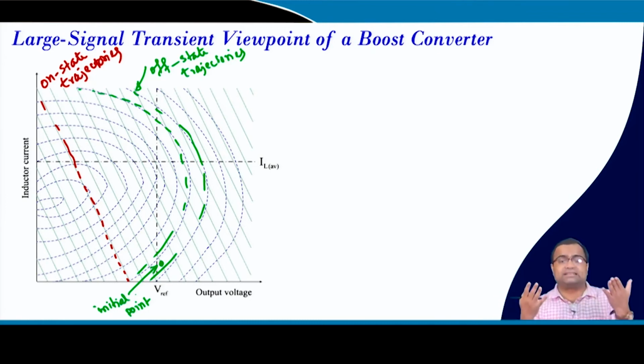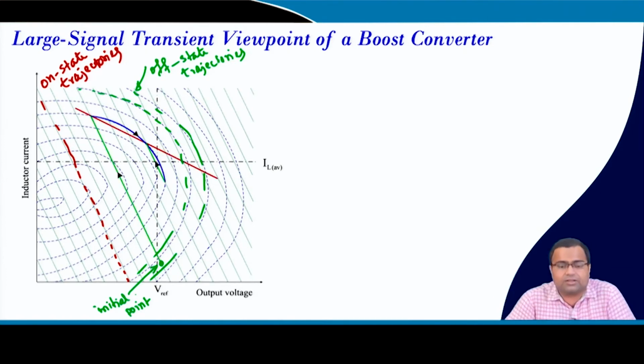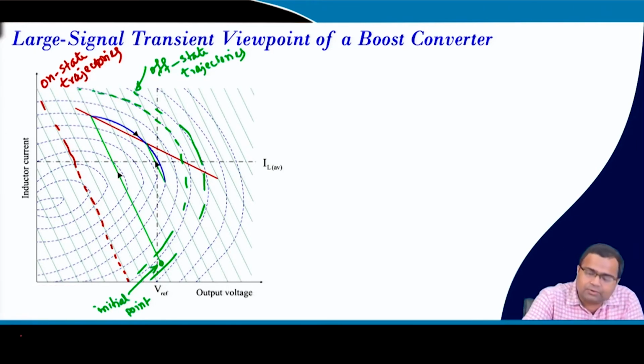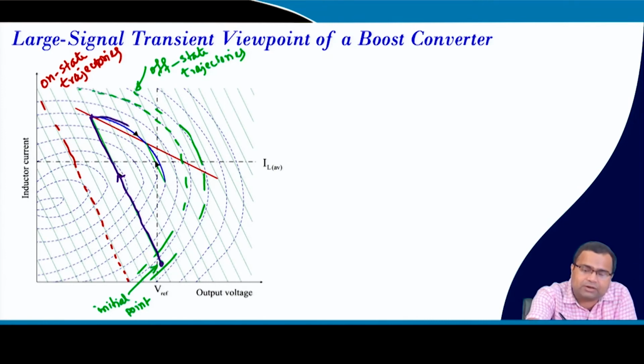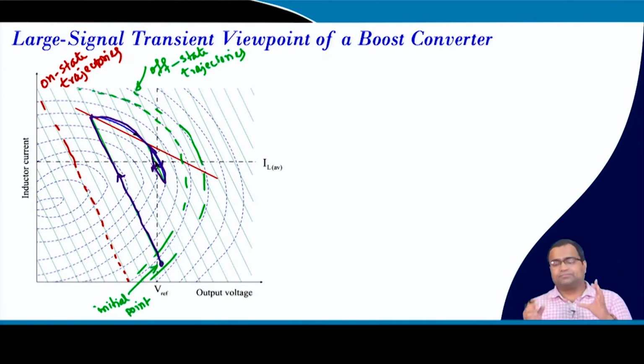I want to reach steady state, and steady state means there will be switching, of course, because if you want a boosting operation, you need to turn on and off, you cannot operate the converter in any particular switch configuration continuously, right. So, this is something like our desired behavior, that means we start from this point, and this is my on state trajectory, it follows this path. Then suppose there is a switching surface which is a first order surface, it hits here and then it turns off and goes like this, and here it reaches steady state, that means this is a steady state action.